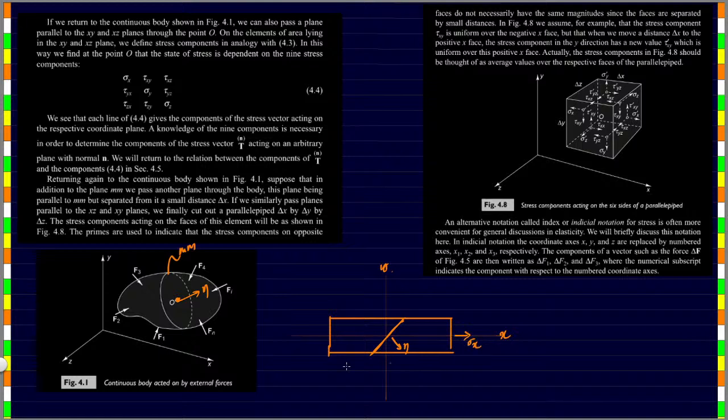So there is going to be a longitudinal stress in this direction, and a longitudinal stress in this direction, and let's say this one is clockwise, this is going to be called tau xy. This is opposite of xy, and in order to balance it, we will have to add the yx. Both are the same. So these are the forces acting on this 2D plane.